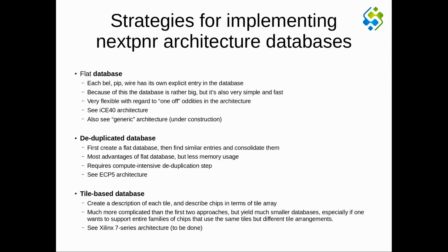So for really large chips, you have to use a different approach, which I call a tile-based database. With a tile-based database, you say, this is the tile structure behind my chip. And I have a small database, in essence, for each and every tile type. And then I just have a large table that tells me which tile in my chip is of which type. And the nice thing here, of course, is if your device is twice as large, the database is only a tiny bit larger. And if you have two different devices in your chip family, the database that covers both of them might only be a tiny bit larger than the database that covers only one of the two.